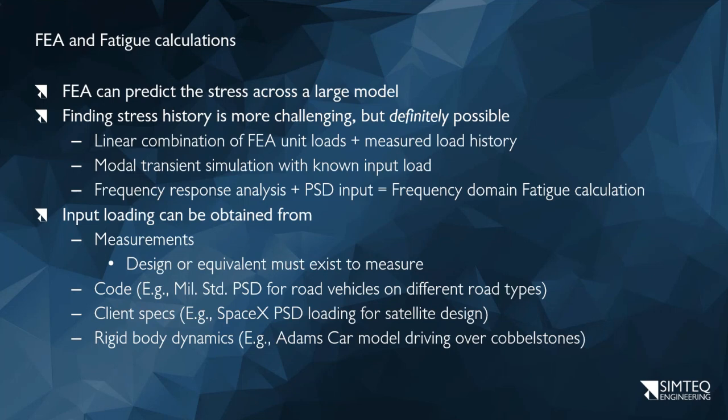If you now redesign the structure to have a frequency that differs from that, and you use it as is, you're actually using the wrong thing because you're exciting it at a frequency which it doesn't like excitement at. So, as I say, you have to be slightly careful with directly using time-based data immediately in that fatigue calculation. In the frequency domain, it's slightly easier because instead of your PSD that you measure, you've got some kind of a curve surrounding that, which extends it a little bit and therefore better represents reality.